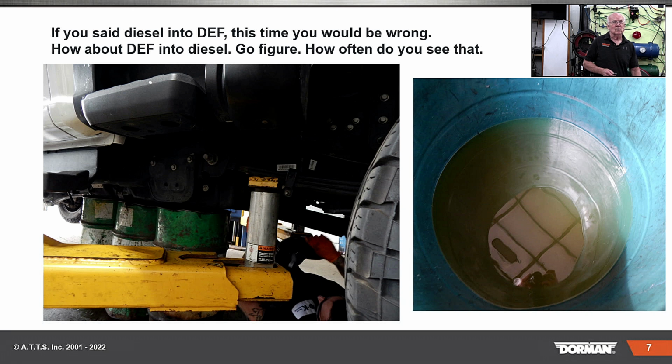The reason you don't want to turn that key on is because your low pressure pump, the minute you turn your key on, is going to do what? Exactly, it's going to try to fill it. So do yourself a favor, get a flatbed. If it's in neutral, we'll roll it off, we'll roll it around the shop.